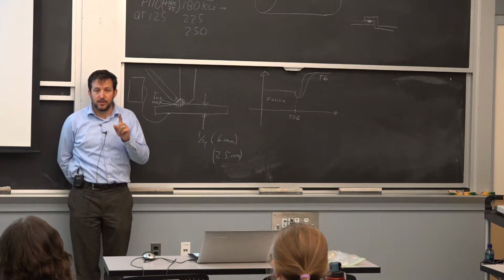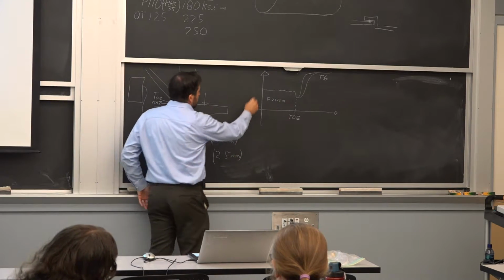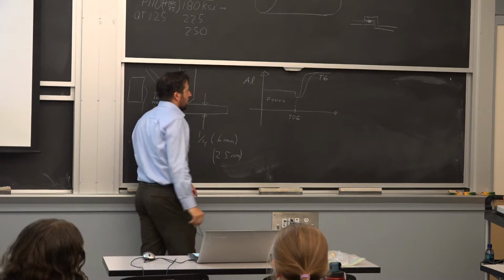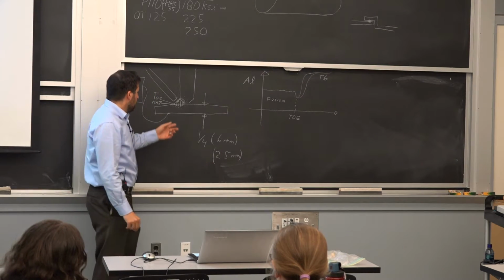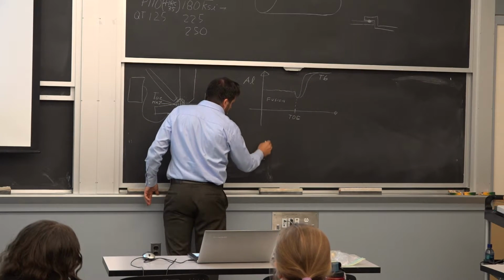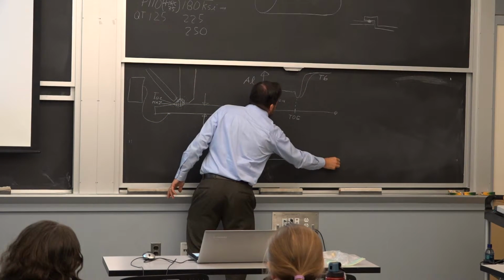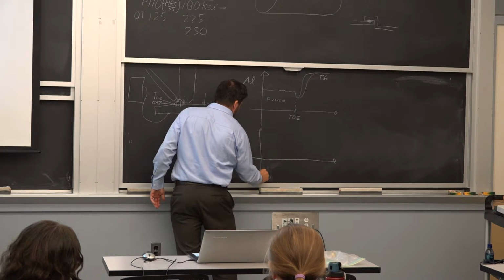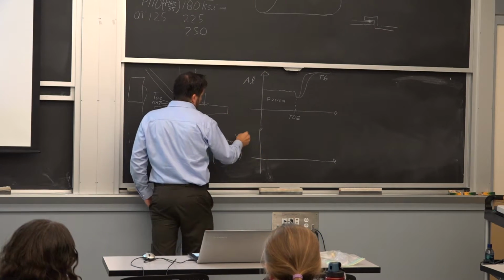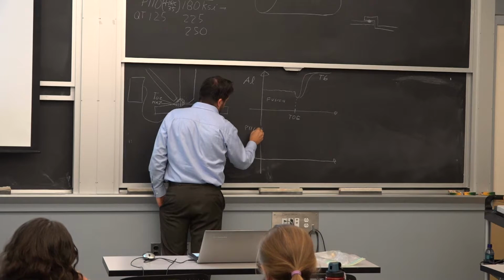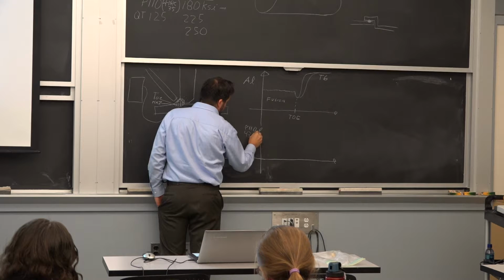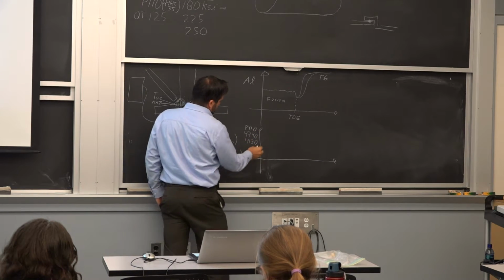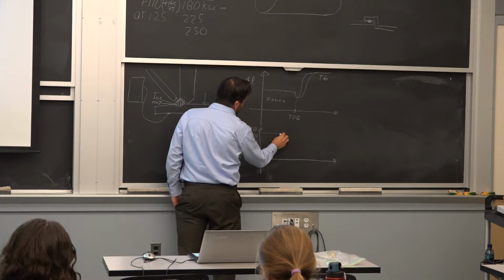Now the best news here for aluminum, it's still very ductile. Nothing happened. Now, when we try to do this with a relatively high strength steel, and try to put it in the same scale, whether it was the P110 or what else we have, we can have a 4340, any kind of relatively high strength steel here is going to have a certain strain in the fusion zone.